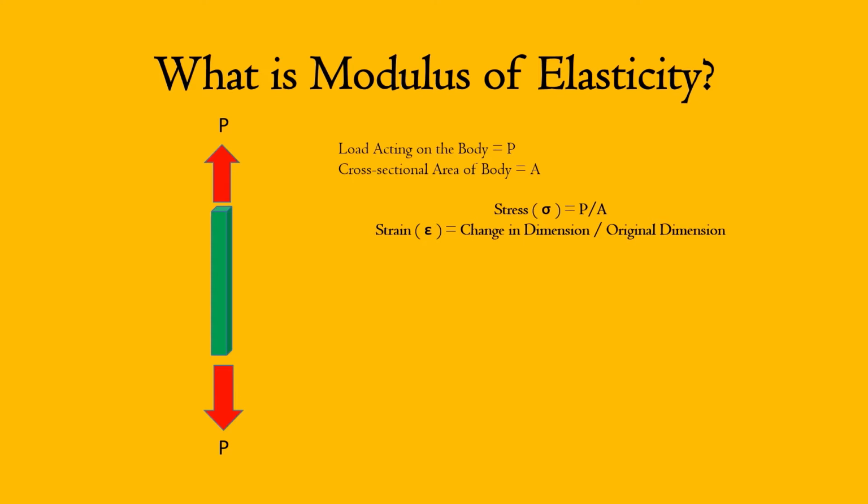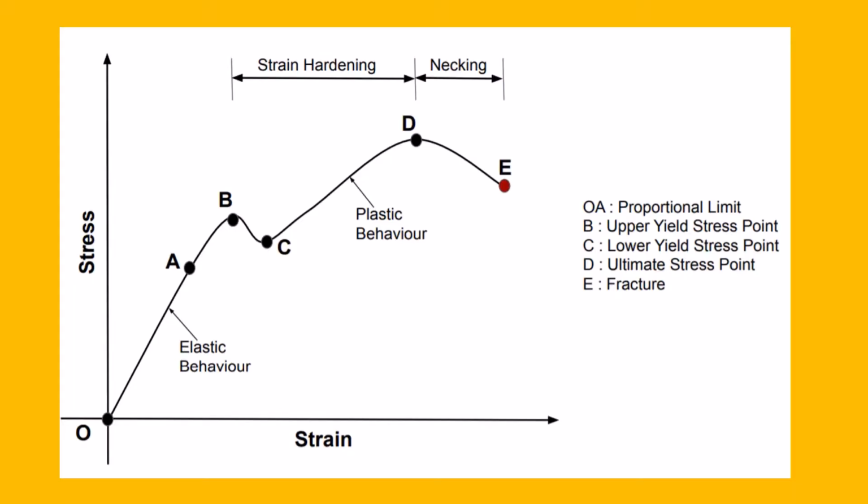If I increase the stress value, I am going to find out the respective strain for each increase in stress value. This method will bring a set of values of stress and corresponding strain, based on which I derive a stress-strain curve. The stress-strain curve is derived for different materials for different load conditions.